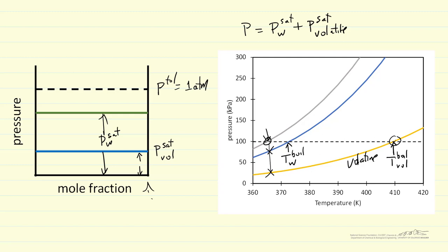Once we've boiled over the mixture of water and the volatile and condensed it, separation is easy because they're immiscible. We get 2 phases, and 2 liquid phases are very easy to separate. Now, instead of adding water and doing steam distillation, it's possible to do vacuum distillation, namely pump away the air. Then we don't have that stagnant air layer and can evaporate the volatile that way. That's certainly done, but steam distillation clearly is used.